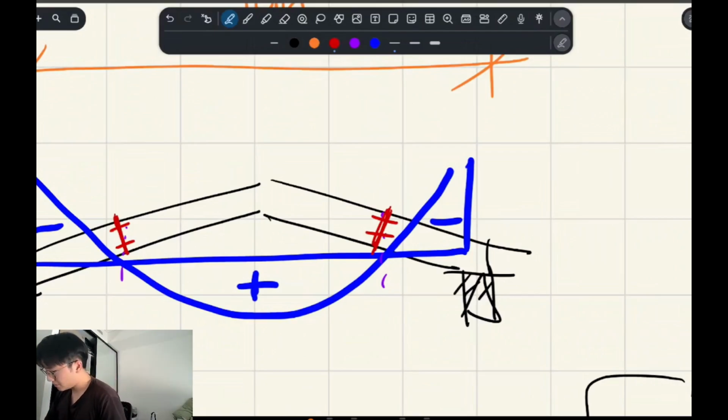There's a few ways you can do it. The way that I see probably the most common is you have an end plate on both. So here's an example of a plate. Specifically, this is an end plate because it's at the end of the member. So you have an end plate at both these I-beams, and you do a continuous fillet weld. So this is an example of where you might weld. Continuous just means all along it.